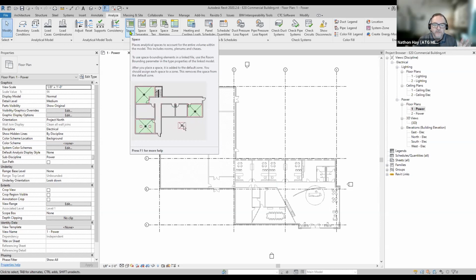That's the only information a room really carries. With MEP, Revit's so powerful that we use something called spaces, because it can use that volume to double check our lighting calculations, to double check our heating and cooling loads. I'm forgetting that those are the 2 main big ones, but rooms won't let you do that.